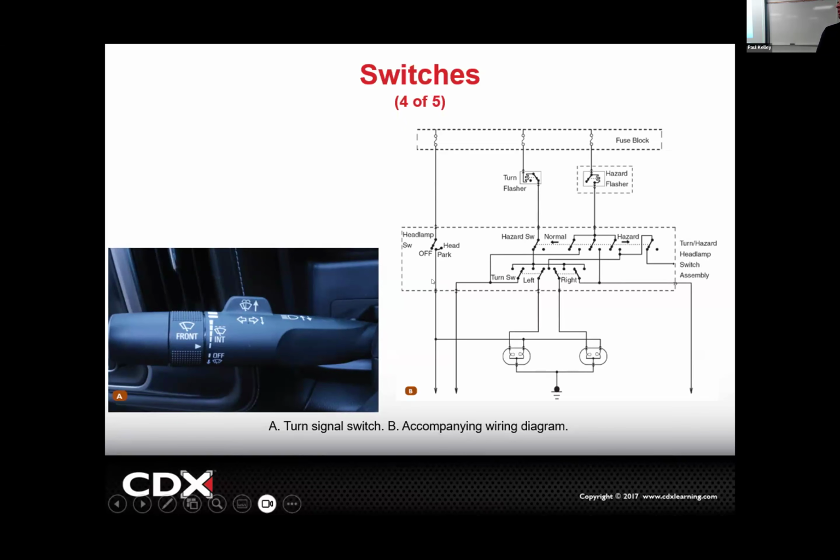That's because there's an open in here. But if 12 volts made it to here, and 12 volts never made it out, and I'm sure the switch is in the right position, we just diagnose that it's got a bad switch, right? But you're not replacing just this part. You're replacing everything in this box, and it's going to look like this. Kind of makes sense?